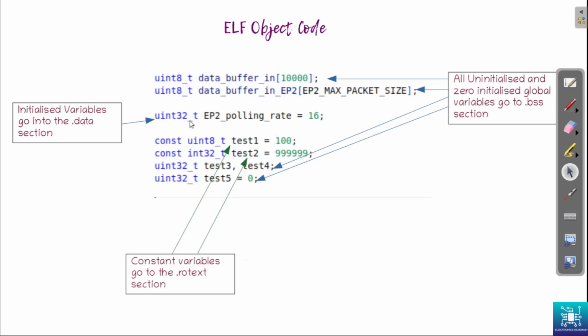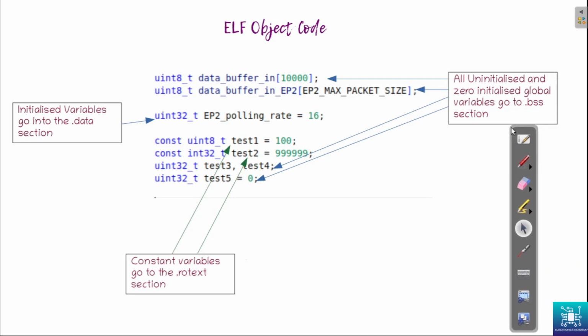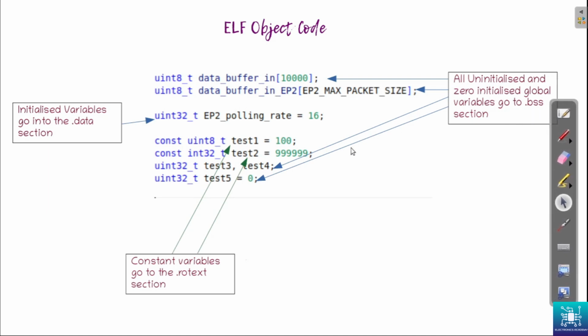Now again, you have one data which is initialized, but it is not constant data. Then you have some constant data initialized here, and then you have some data that is uninitialized. So we have different types of data. Just to validate what happens, we have declared this data outside the main, so that we get a full understanding of which data goes where.